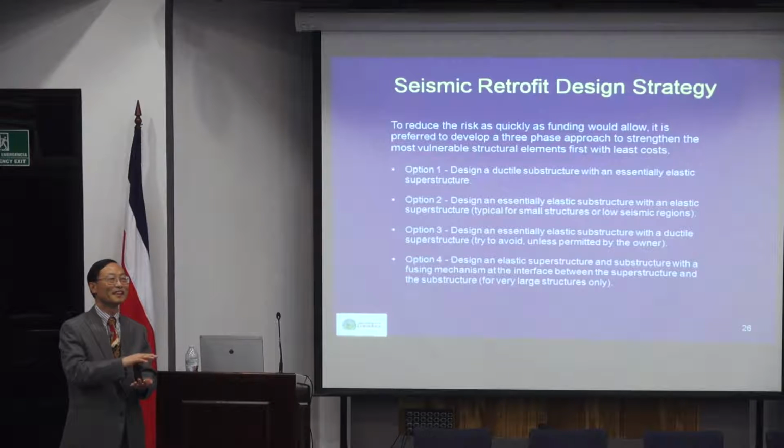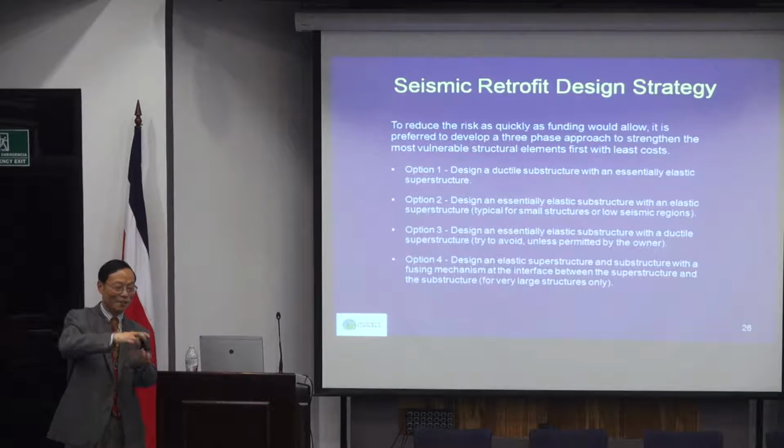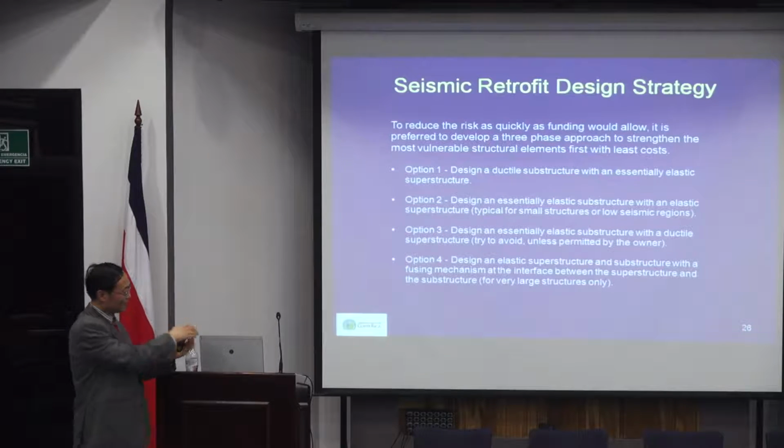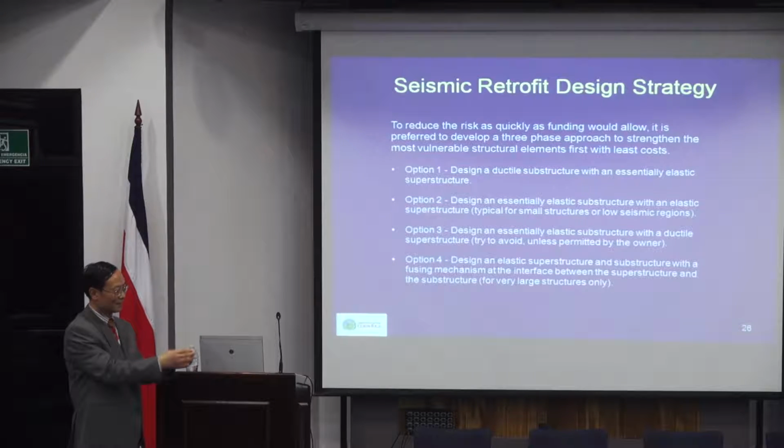But in reality, you cannot have a hinge because the whole structure is not stable, because of the mechanism. So what you do is make that link very weak here. Then I have a bending moment capacity here. Once I know the bending moment capacity, the bending will not be larger than my capacity, so I will know what the maximum earthquake load will be.